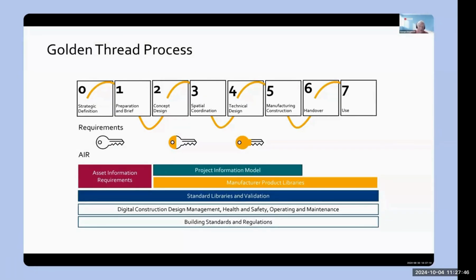It's integrated with the BIM modeling tools, so that we've got the APIs into Revit, which connects everything together so we know where things are. That can then produce a digital O&M and the asset information model in any system. Part of what John was just showing you is that the whole thing is designed around COBie, the international standard for handover information, so it can read into any software application that the clients are using.